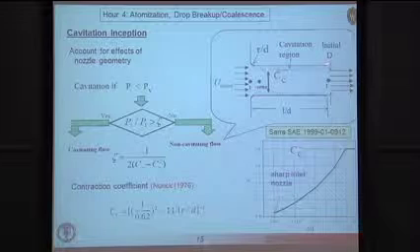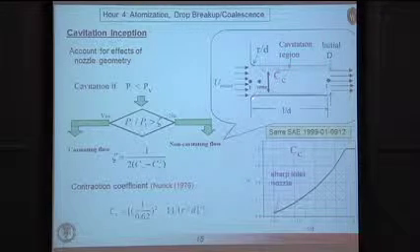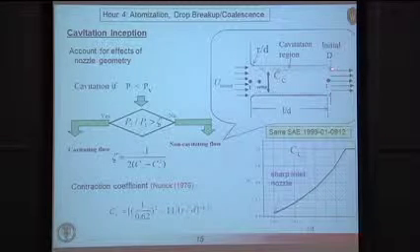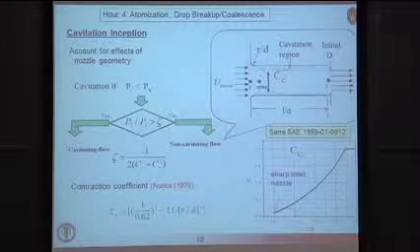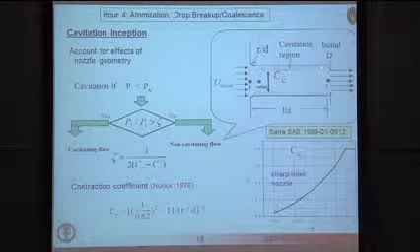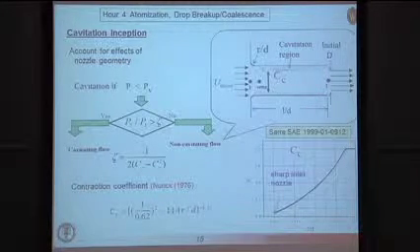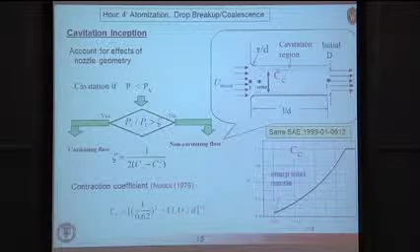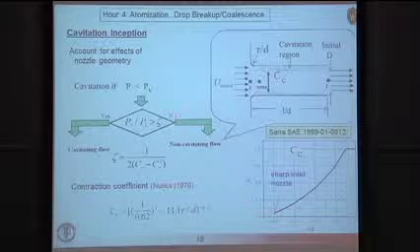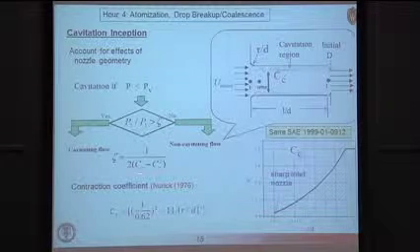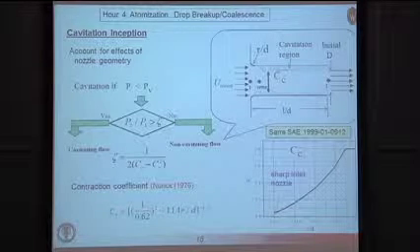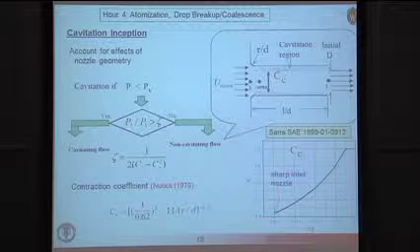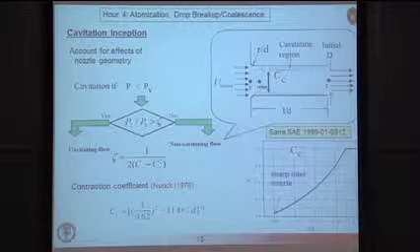So this cavitation region, as you saw in the movie also, essentially can extend all the way downstream. And what we're interested in is the effective diameter of the jet when the jet leaves the nozzle. It's not necessarily equal to the nozzle hole. And also the effective velocity of the flow. So how do we predict cavitation? Well, essentially there's this parameter psi here, which is related to the contraction coefficient, that tells you, looking at the pressure downstream and upstream, whether you have a non-cavitating or a cavitating flow.